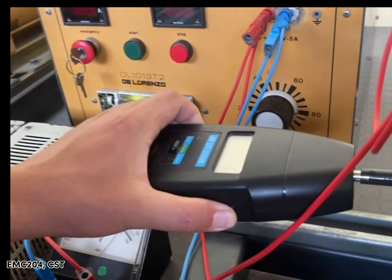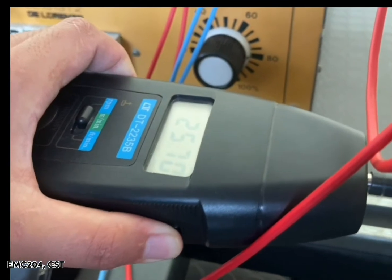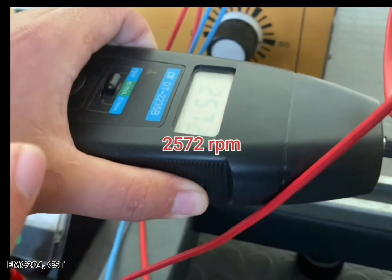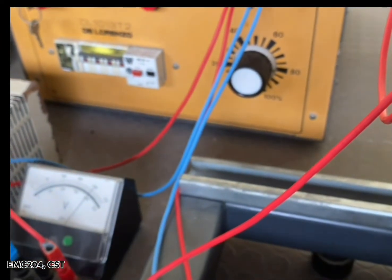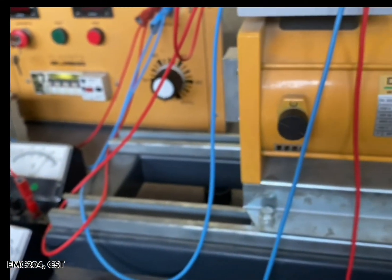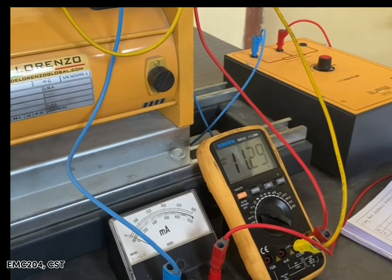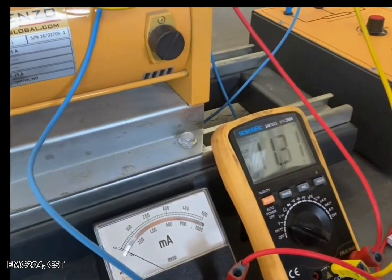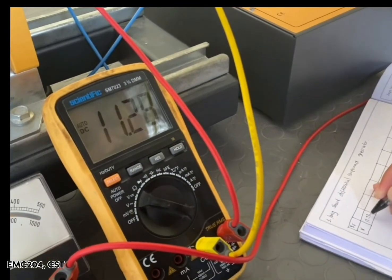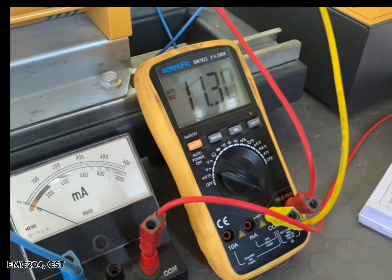Firstly, we have to measure the motor speed. Here, the motor speed given is 2572. The speed in this experiment must be maintained constant throughout. After giving supply from the power supply, we got the residual voltage of 11.33 volts at 0 ammeter.